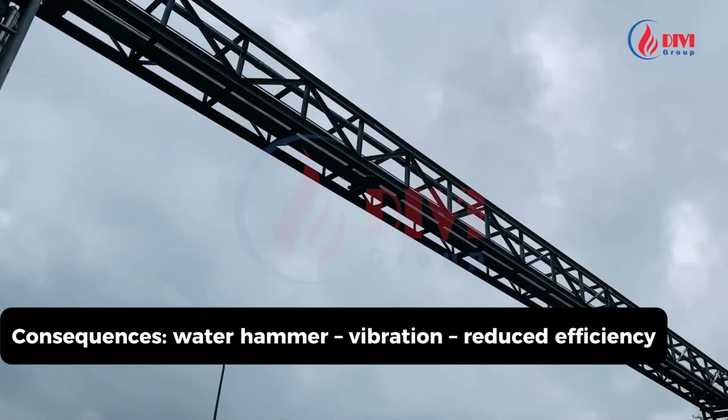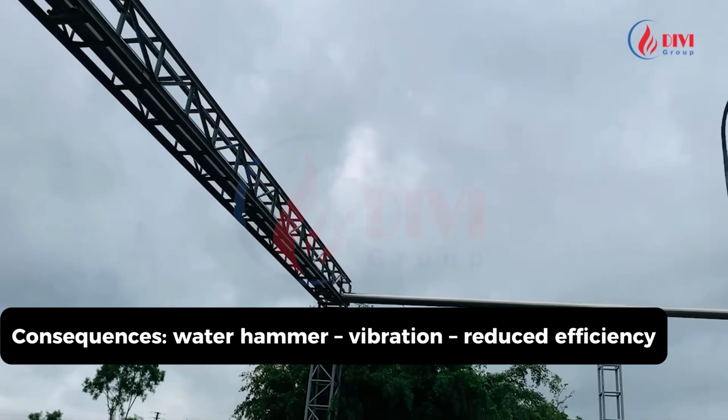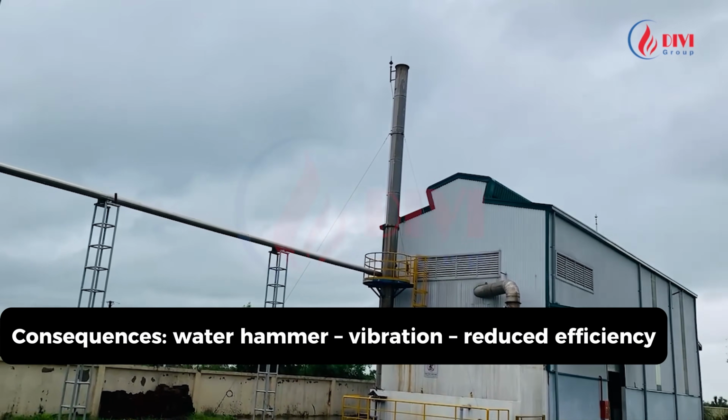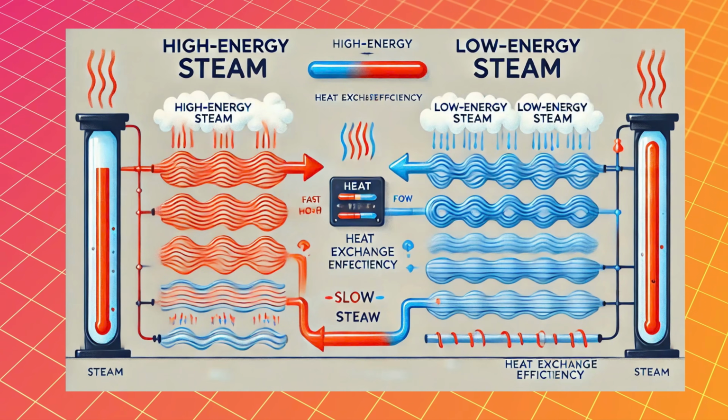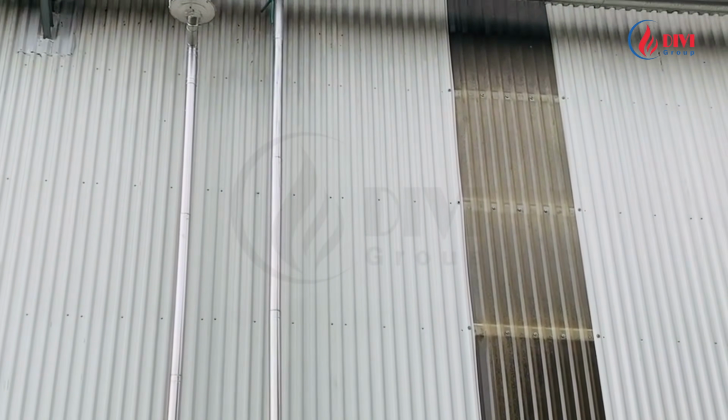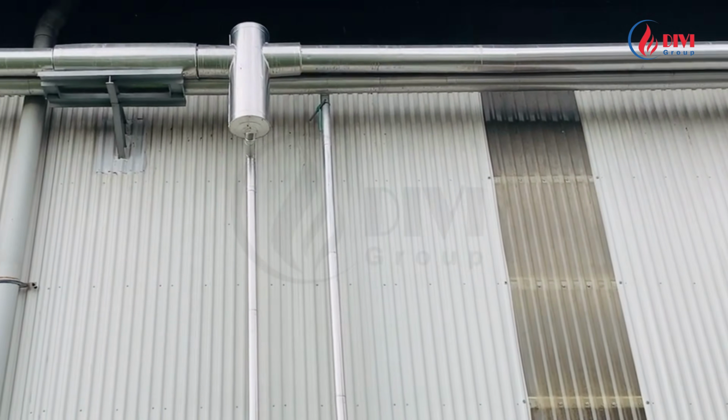Without separators, it accumulates in exchangers or elbowed pipe sections. This leads to water hammer, which causes strong vibrations in both pipes and connected equipment. It also reduces steam energy and heat exchange efficiency. Installing separators every 30 to 50 meters is crucial.